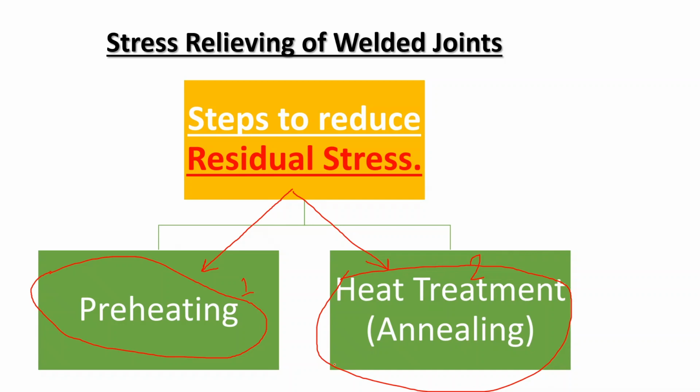It not only reduces the residual stresses, but it also induces residual compressive stresses. Now, these residual compressive stresses are good components, contrary to the residual stresses. The compressive stresses prevent the spreading of the fatigue crack and thus improve the fatigue strength of the joint.